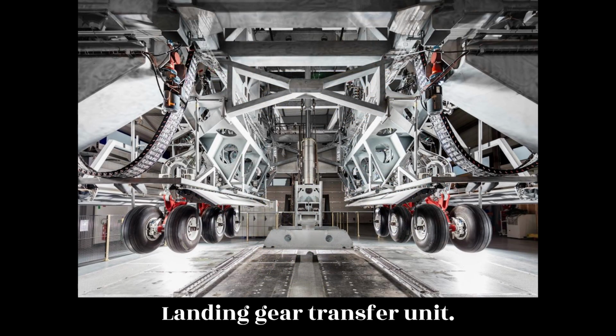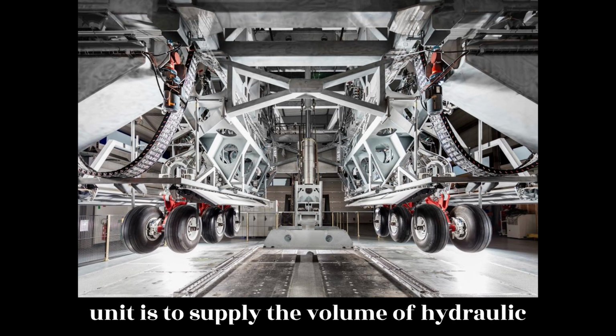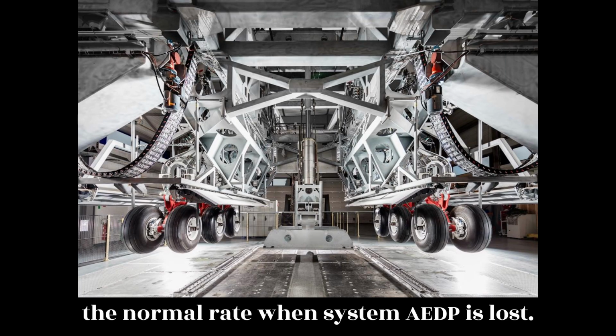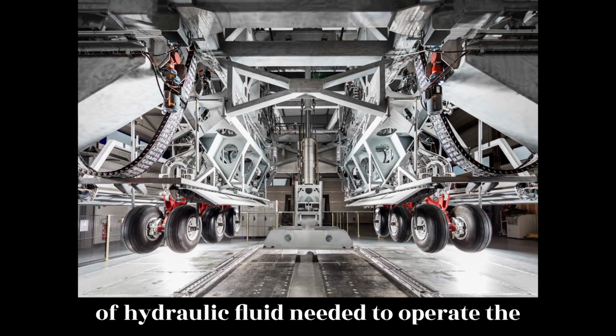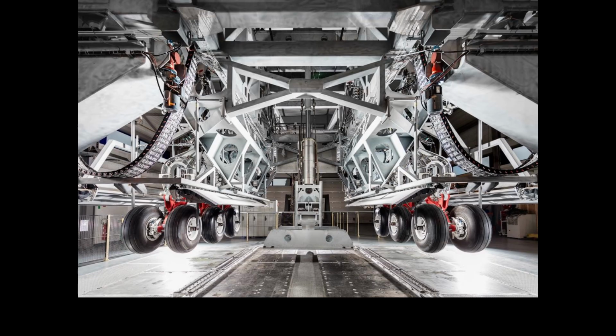Landing Gear Transfer Unit. The purpose of the landing gear transfer unit is to supply the volume of hydraulic fluid needed to raise the landing gear at the normal rate when System A EDP is lost. The System B EDP supplies the volume of hydraulic fluid needed to operate the landing gear transfer unit when all of the following conditions are met.